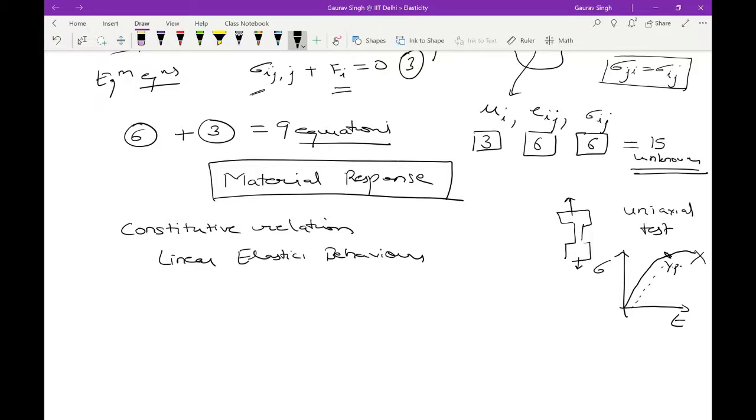Now, one of the other things, as you know, is that a ductile material would show some sort of a large deformation before it actually fractures. So consider, say, a material like aluminum. It will go up and it will go something like this. This is aluminum fractured. Now for something like steel, it will go up and then come down and then go up again. This is again steel. Okay, but for say a brittle material like cast iron or wood for that matter, you can have a straight line which will become only slightly nonlinear and fracture.